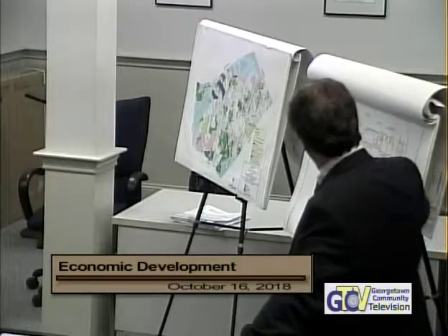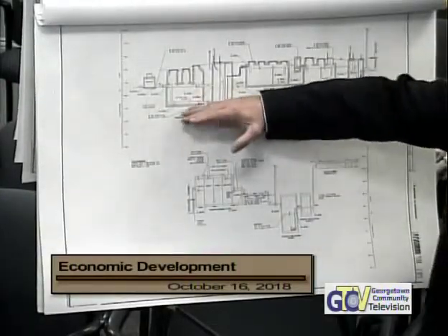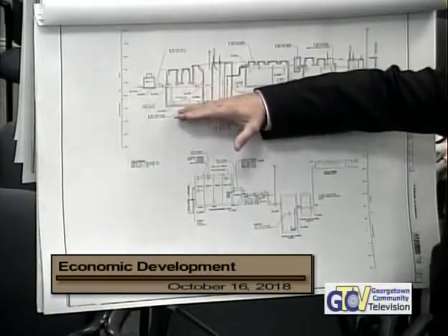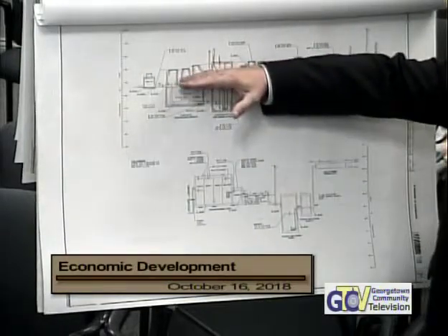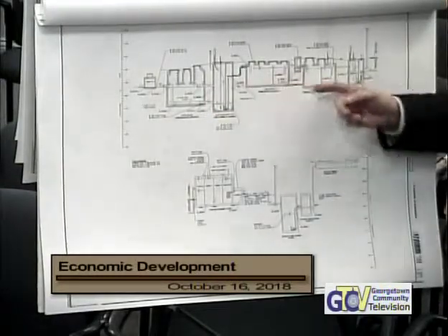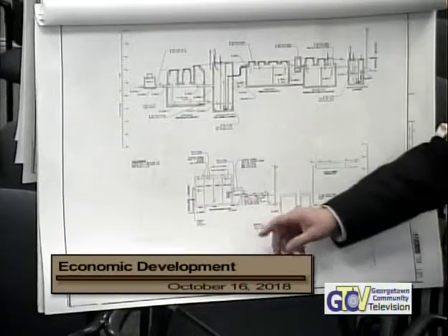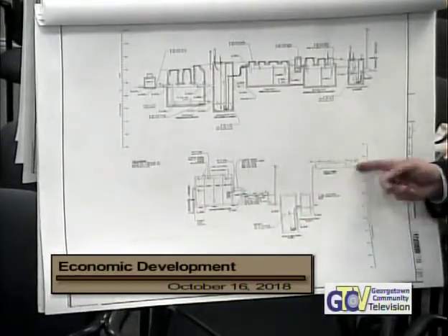This gives you a rough schematic of how the treatment tanks are laid out. The flow equalization tank basically allows the flow to go up and down, okay, as it comes in, and it gives a metered flow out to the other tanks for settling, pumping to the treatment process, the membrane reactor tanks, and then pumping out to the disposal field.